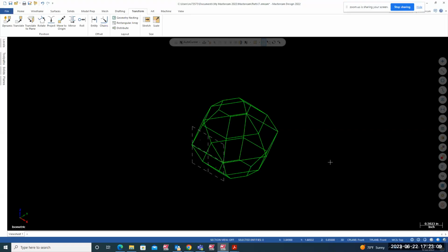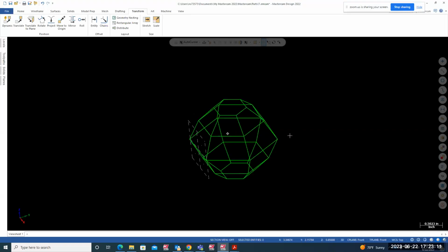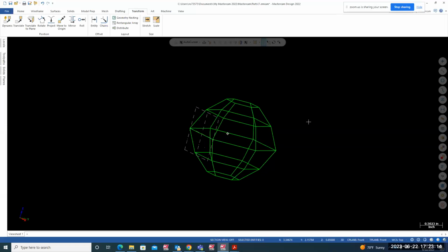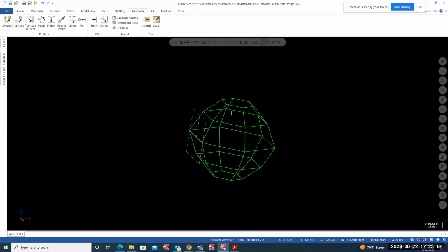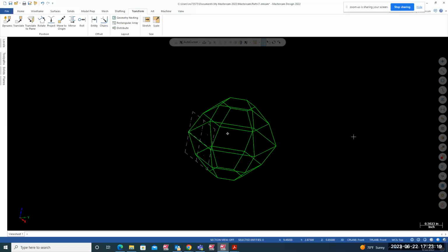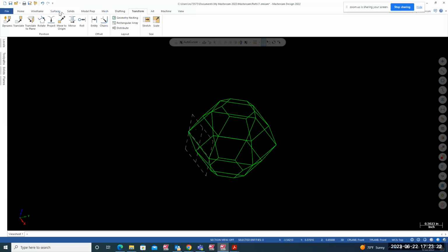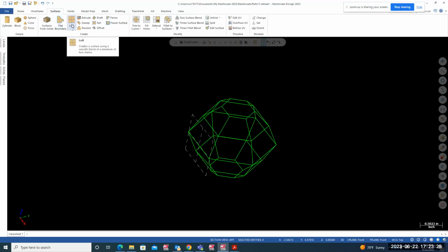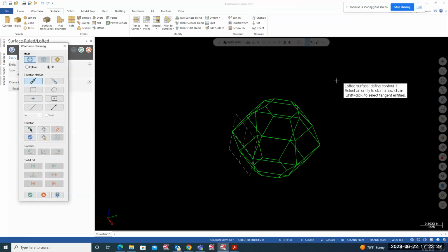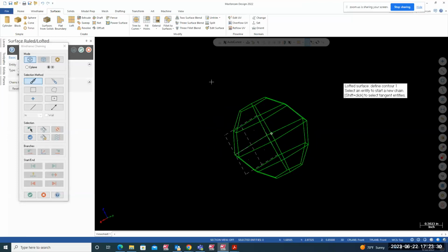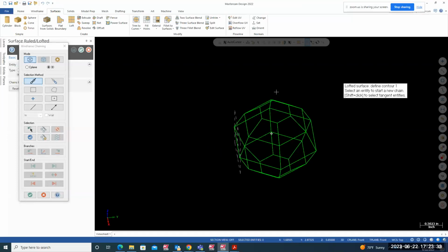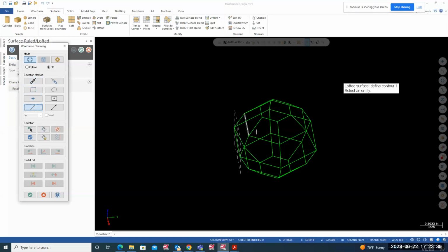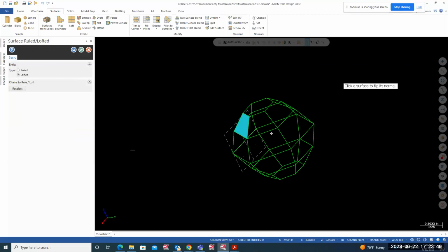But I need the surfaces on all this. There are my surfaces. So to create the surfaces, I can use, here, go to surfaces, I can use loft. And with loft, you can create a surface on each flat. So I can go single, they're all single. This is my first one. I can go first, and then I can use my second and apply, hit OK. And there's my surface.